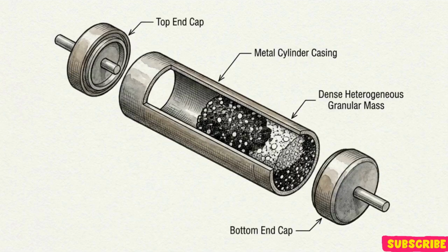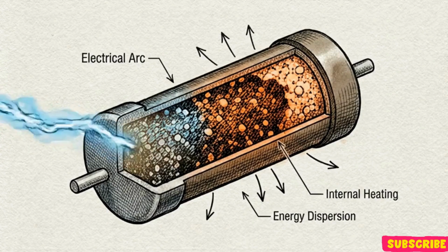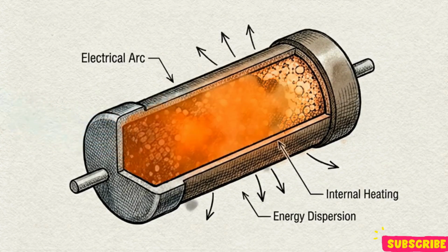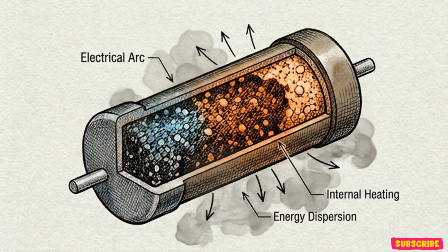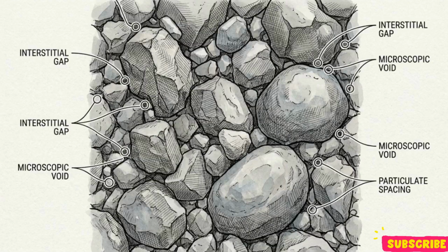This photorealistic CAD cutaway reveals its internal architecture. It consists of a solid, macroscopic volume of carbon powder bound together with a ceramic filler. By utilizing a dense, bulk mass of material, the component achieves massive thermal capacity, allowing it to absorb high-energy, sudden transient voltage spikes. The internal structure of the carbon and ceramic mixture is entirely random.